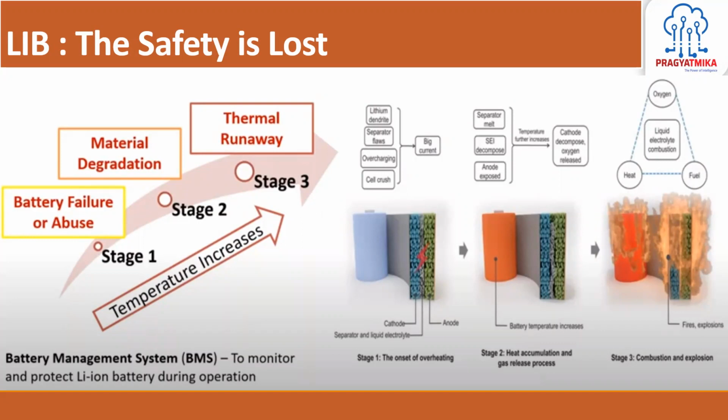Many people who are involved in fire dousing and fire extinguishing also see that if a fire is caught in a battery pack and you use water, that also creates an issue. If you use normal fire extinguishers, that also does not create an insulation between the air oxygen and the battery pack properly, because there is already an oxide inside. So halon-type fire extinguishers are generally preferred over here.